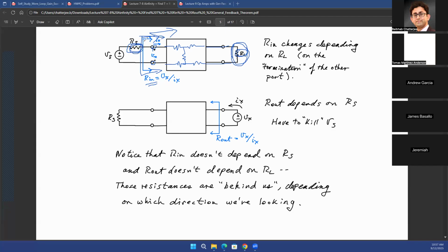that will not have any impact on the input resistance if and only if you're looking at the input resistance from this point onward. So you're defining your input resistance at the right-hand side of RS. So whatever you connect as RS does not matter, right? If you're looking at the right-hand side of this particular terminal, it does not matter what is connected to the left. So on the input impedance, RS does not have any impact, but RL can have impact.